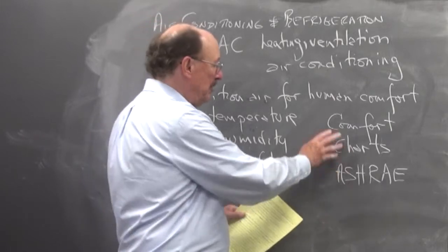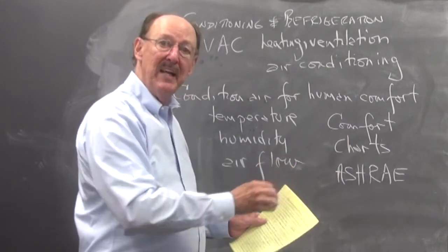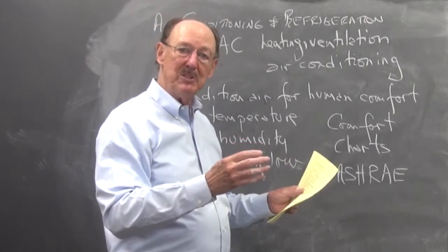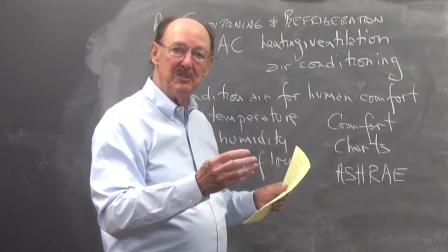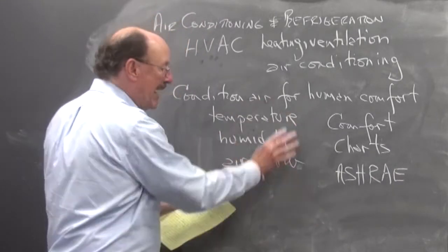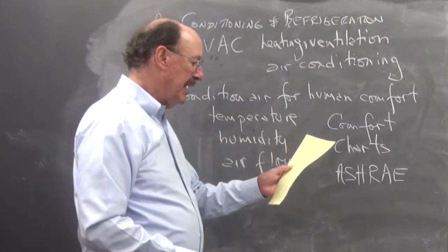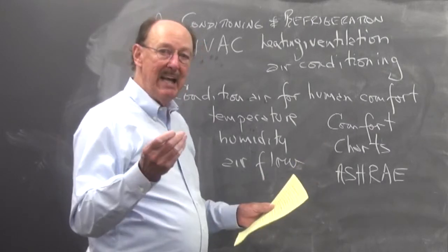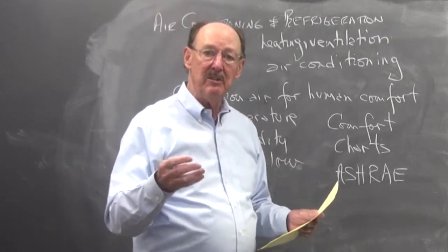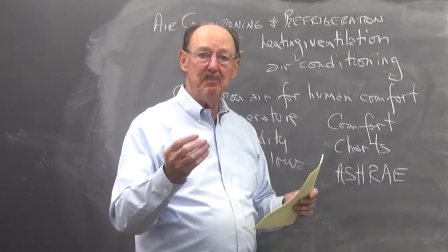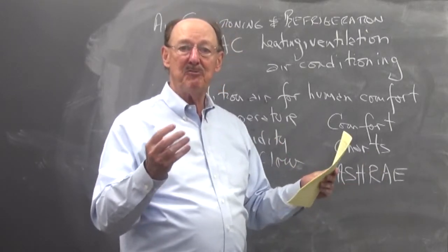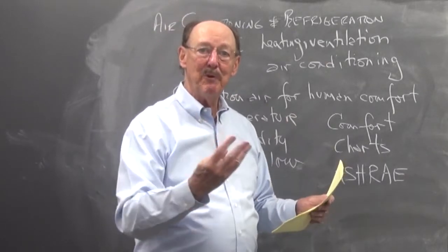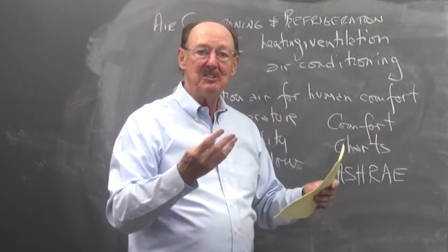But what they've done in terms of a comfort chart is that they've done experiments with people, and they've looked at people say what was comfortable in different situations in terms of these factors and other factors. And I thought you'd find it interesting, just the outside airflow. So one of the things we have to consider when we're air conditioning buildings and spaces is how much fresh air you have and how much recirculated air you have. So the fresh air, you want new oxygen to come in.